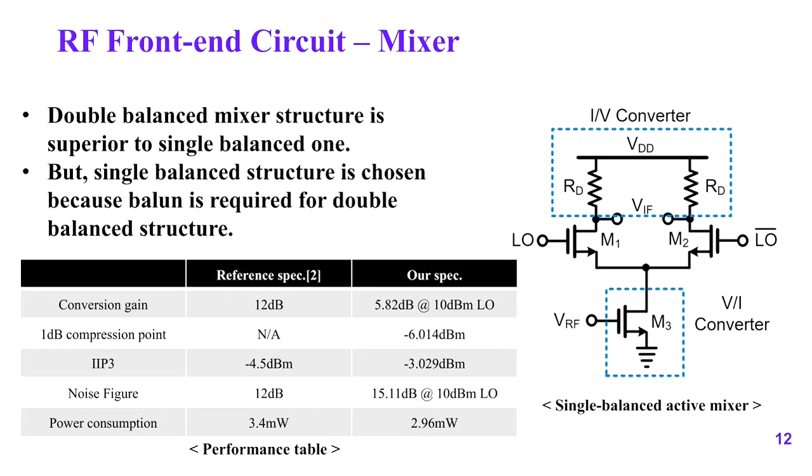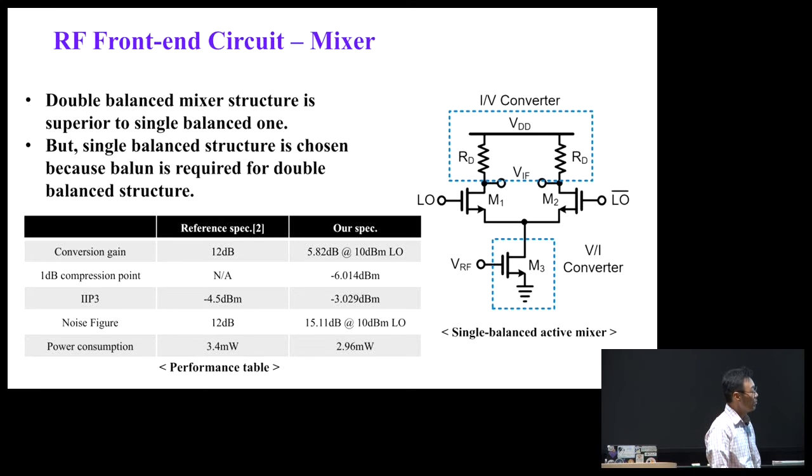So this is just a simple schematic of the mixer. Another issue is, again, the inductor. Imagine the antenna is just a single device. But to design a common topology such as a double balanced mixer, we need to convert the single-ended RF signal to a differential signal.